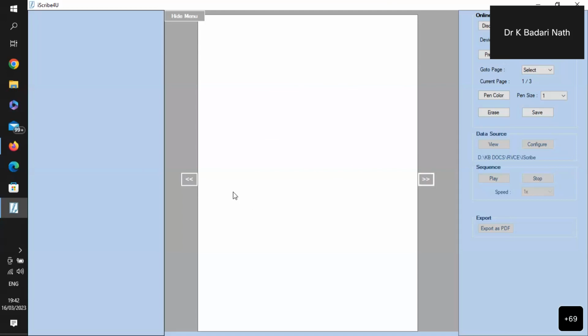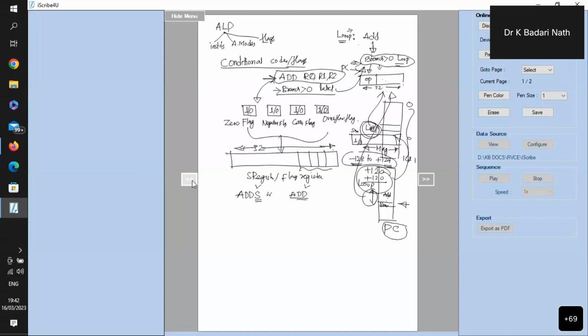What is the difference between assembler directives and assembler instructions? Sometimes when we write a program, like this: ORG 00000. I write my instructions here, all the ADD or whatever is required. Then I say ORG 2000, in hexadecimal. Then I reserve my data here.